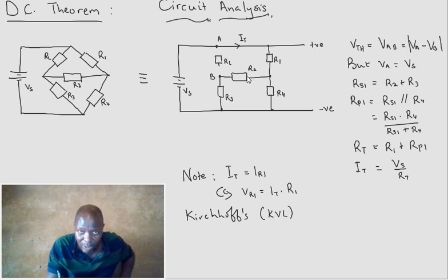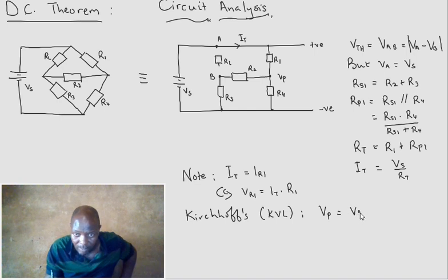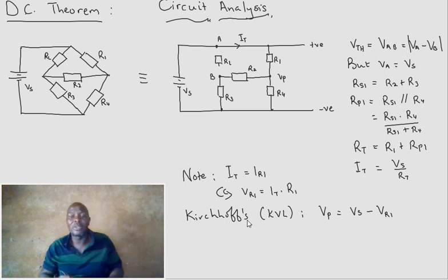So that value is one value, a parallel value. So this is V parallel, the same value. So VR1 plus V parallel will give us V supply, which makes our life easy, because now we know what V parallel is. According to Kirchhoff, V parallel is going to be V supply minus VR1, and we've worked out VR1, so it's not been difficult.